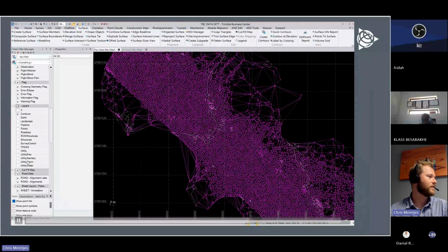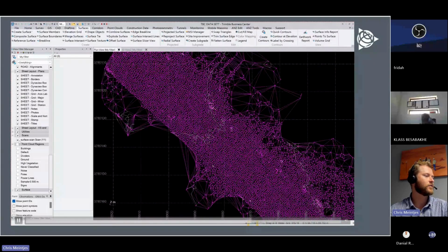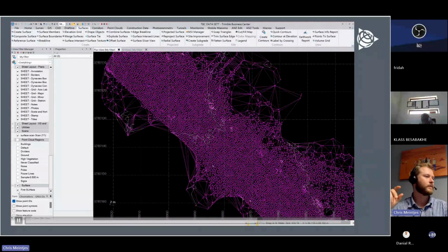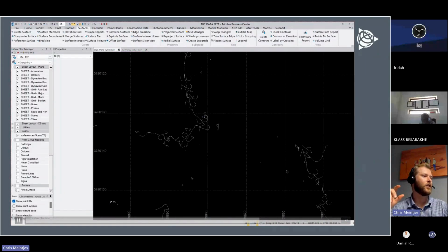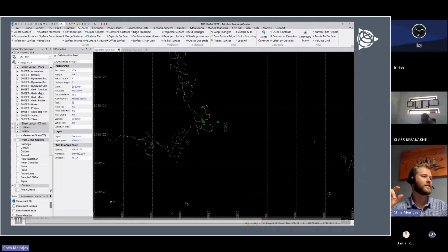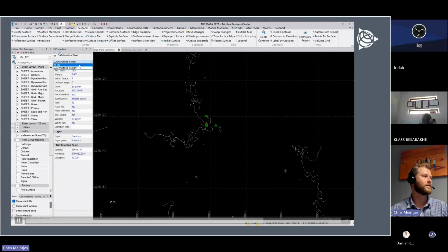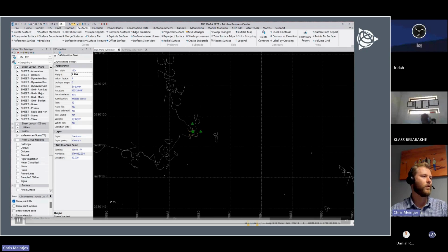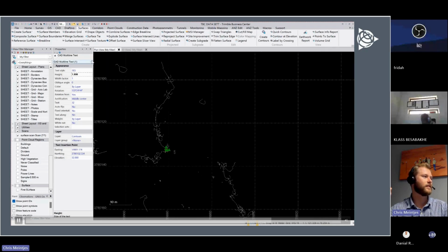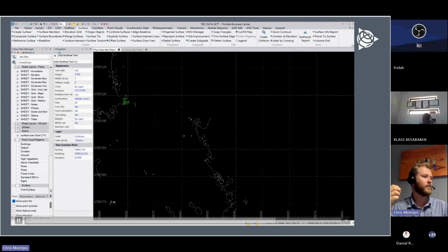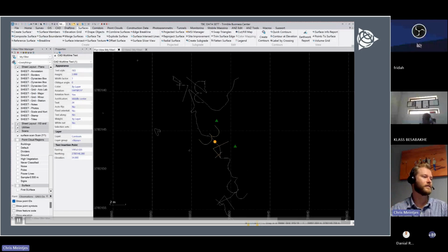With the text, the best way I've found to edit it globally is this: you can click on each individual text, so basically a contour label, and edit it. You can see that they sit along the contour line. I'm selecting it. You can move it. You can edit one at a time, like I'm doing here. Make it half as small. Or what you do, as you're going to see in this video, is select them all and edit them all at once.